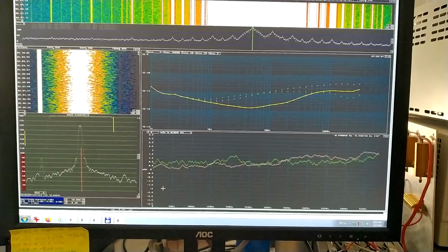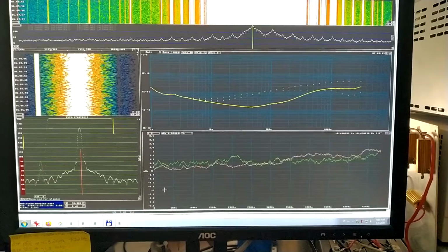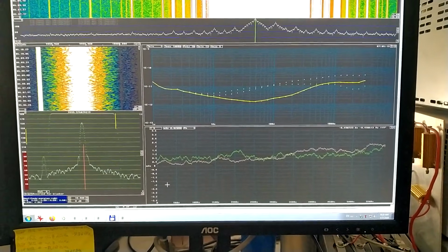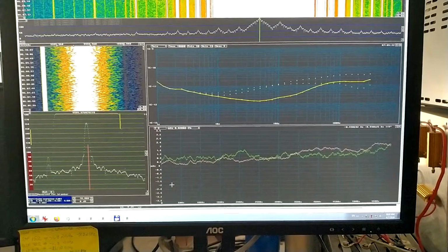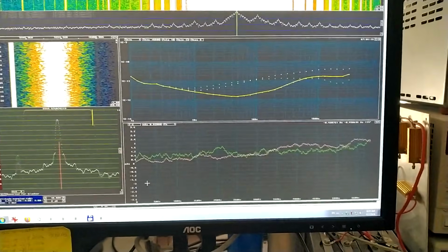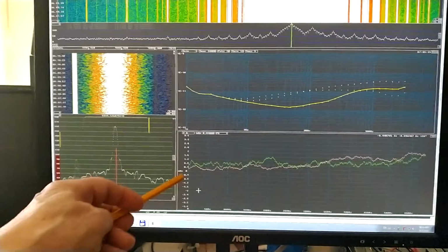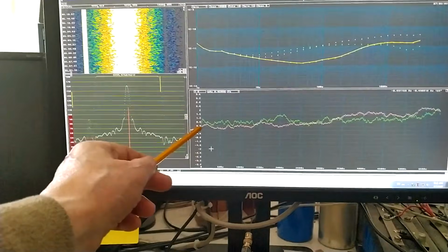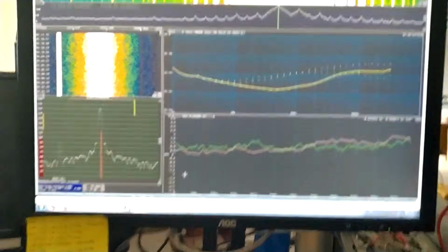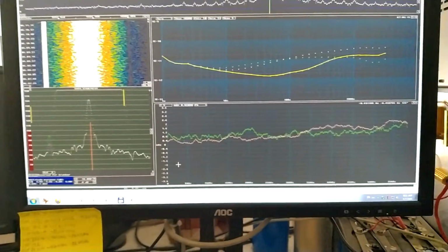Now the 2 oscillators with 4 crystals in each one are the reference oscillators for my Linrad system. Both of them are phase locked to the frequency shifted rubidium source, and the signal source is another rubidium source. And the frequency versus time, it has a drift. When it started, those traces were at 0, the latest 5,800 seconds, that's 1.5 hours, I think, is what you see in the graph.